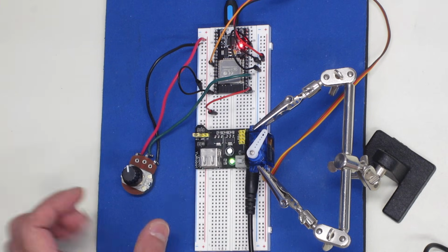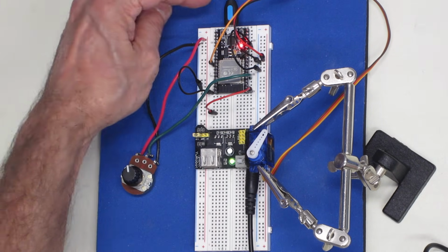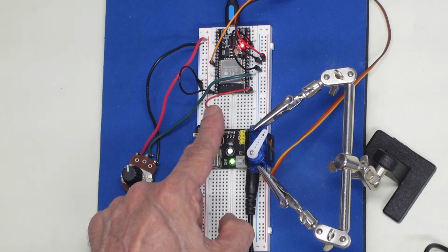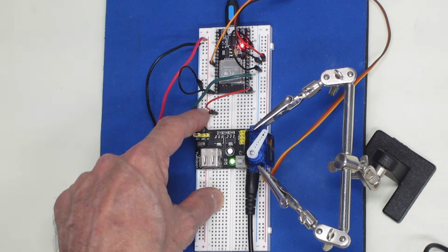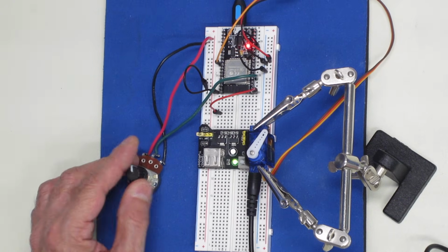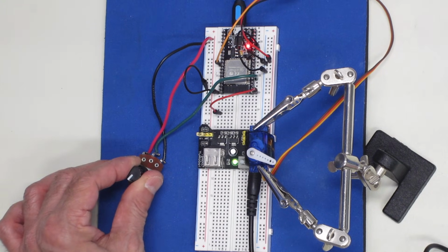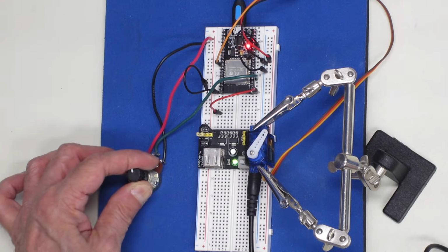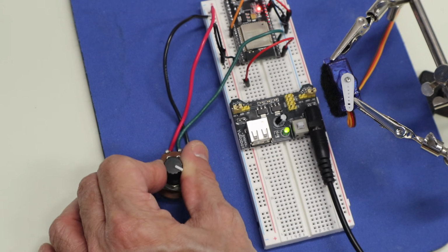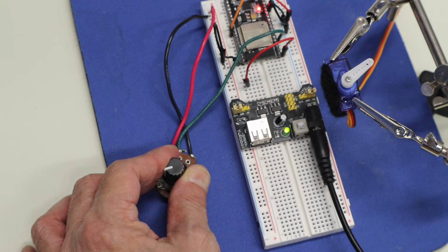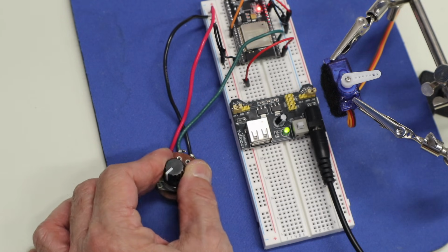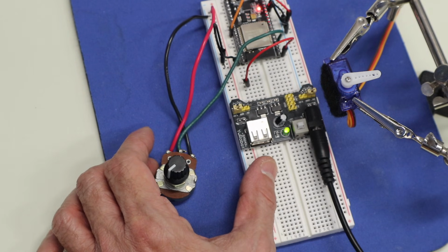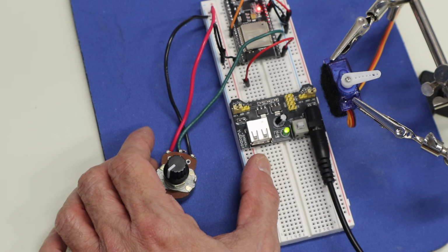5 volts is still powering the servo, of course, and if I were to disconnect this cable from the computer, I would need to connect the power, that's this red line, to the 3.3 volt rail. So having said that, let's go and see if this works, and it does. As I'm moving the pot, I can put the servo into different positions. A very simple sketch, and it just emulates the original Arduino knob sketch, but it'll give you a good idea of how to work with servo motors with the ESP32. So now that we've seen that, let's move on to the next step.